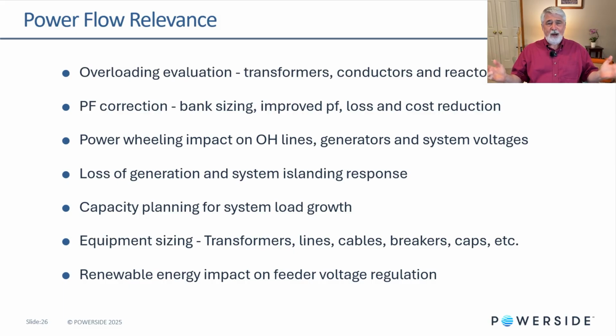Often in industrial power systems, we just add the loads up and say that's it. But that's not all of it. Those loads flow through components. They flow through transformers, they flow through cables, and they will have additional real and reactive power losses. So if you want to know your total load on a system for capacity planning, run a power flow simulation.